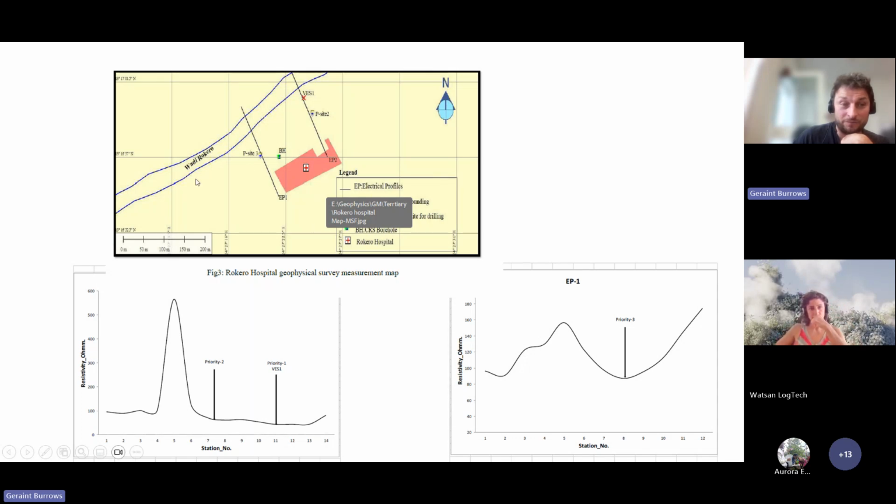However, in this particular report there wasn't any structural analysis done. If they'd looked at topography and a regional geology map and seen that structures were running this way, north to south, then they might have decided we should have done one more profile across here, to see if we could pick up anything structurally interesting that these lines might miss or might not pick up very well.